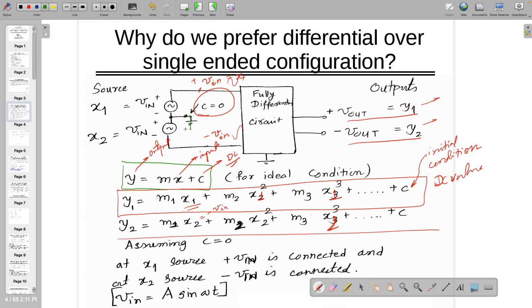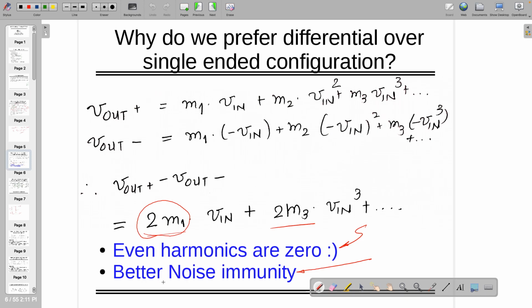Okay, so here there might be DC, sometimes it might be AC also, right? So both same, then it's common mode. So in that case also, this common mode is going to be removed, right? If both the networks have the same thing going, then it's removed. So we should not say only that it's giving better noise immunity, but another way to say this is that common mode noise is removed. Whatever is available in common mode noise gets removed, becomes zero, right?